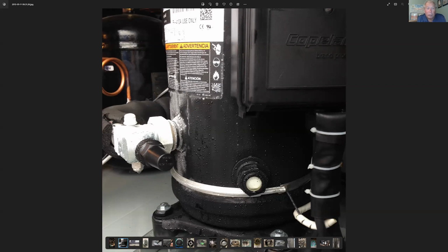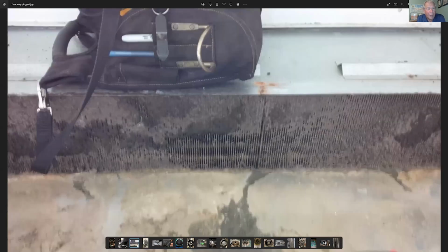I think what we always simply termed, or tried to use the term, was anytime the evaporator loses its load or control of the load, whether that be through a low load situation, somebody turning a thermostat or refrigerant controller down lower, or the airflow across your evaporators. There's a nice, clear example of a not so clean coil, but very clear if you look at that from a service perspective. This thing hasn't been maintained in who knows how long, Trev. Anytime you lose that airflow, or it's just flat plugged right there.